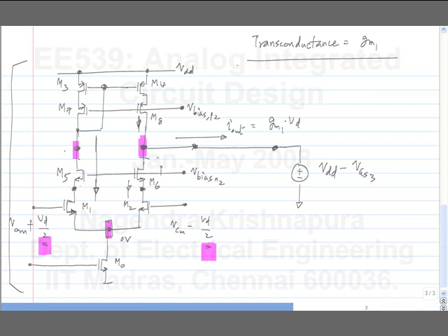So transconductance we know. What is the output conductance? For output conductance, we have this bias, we apply an increment over this, and the input increment is 0. So let's say I apply an increment on top of this, and I measure the current that's going here.